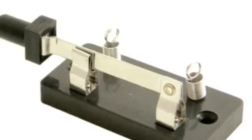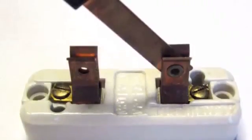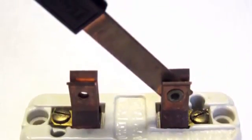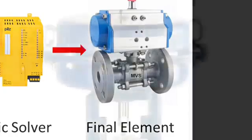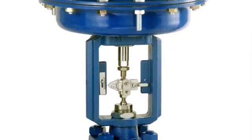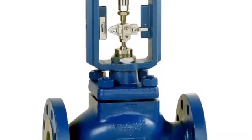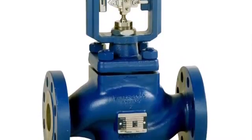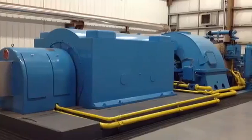If the signal level is determined to be outside of the safe operating limits of the process, the safety relay will open. The safety relay state, is it open or is it closed, will determine what action the final element will take via a hardwired connection. The final element must now take action to perform the safety function. An example of a final element is a steam cutoff valve to a turbine generator. The valve, or the final element, can quickly close to cut off the steam that passes through the generator's rotor in order to stop the rotation.